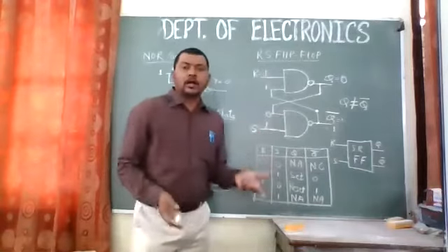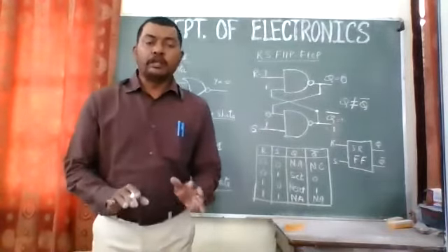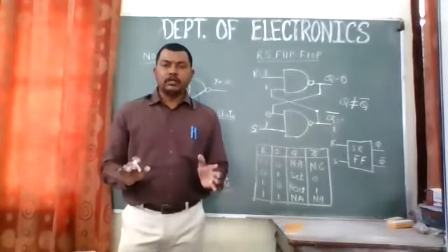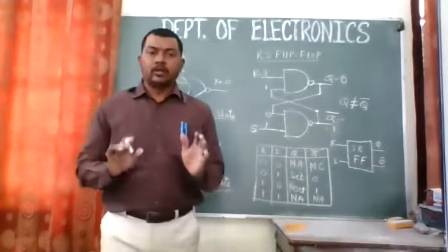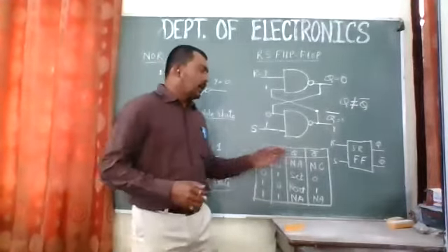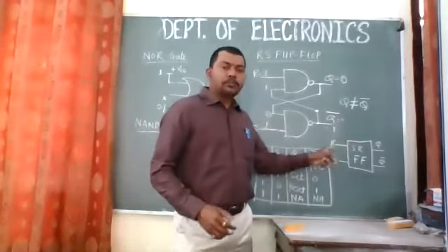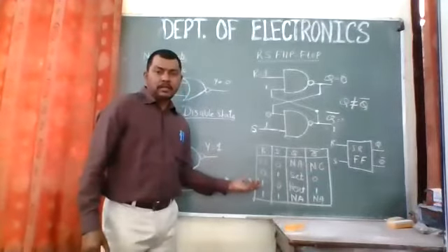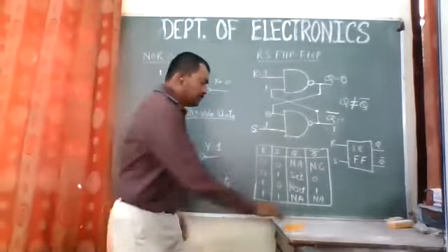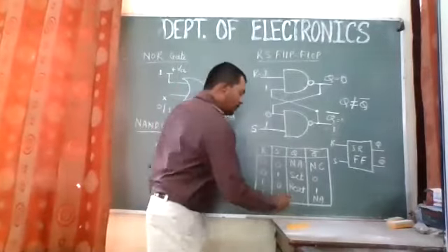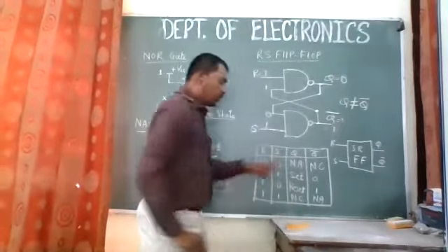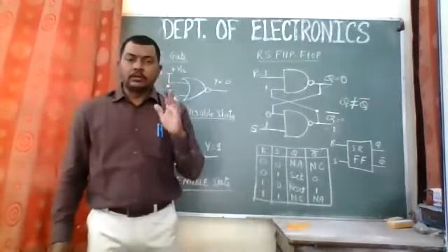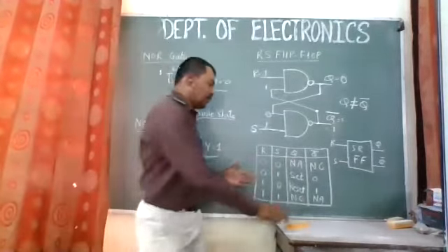So these two conditions are only going to change when we employ NAND gate to implement a flip flop, right? I guess you have understood the flip flops by using NAND and NOR. From the next classes, I'll be just using these sorts of blocks where I'll be putting R, S, and the output Q and Q bar. The truth table is the same like this, just for NAND and NOR, the outputs are going to change over here. So here it will be showing not allowed condition, and here it will be showing no change. But the ideal truth table is like this only.